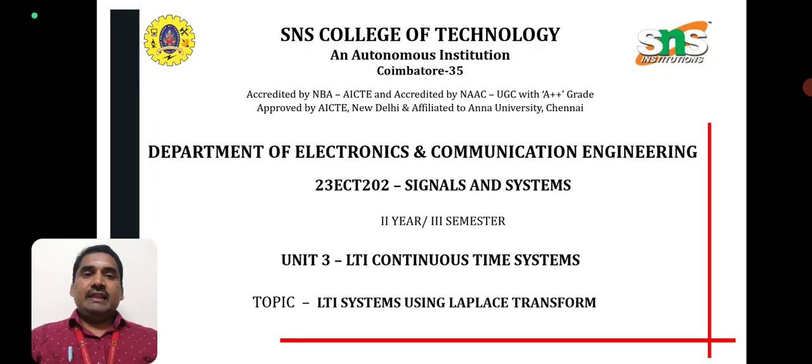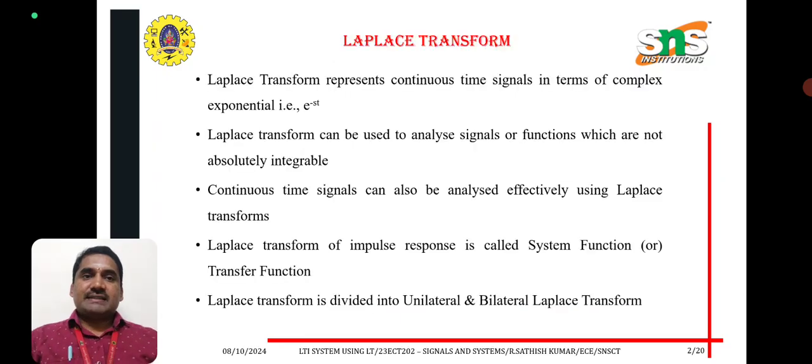Now let us see another video lecture series on linear time invariant systems using Laplace transform. Laplace transform represents continuous time signals in terms of complex exponential, that is nothing but e power minus st. Laplace transform can be used to analyze signals or functions which are not absolutely integrable. Continuous time signals can also be analyzed effectively using Laplace transform. Laplace transform of impulse response is called the system function or transfer function. Laplace transform is divided into unilateral Laplace transform and bilateral Laplace transform.